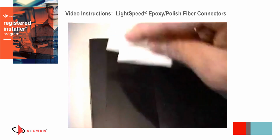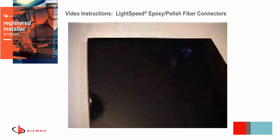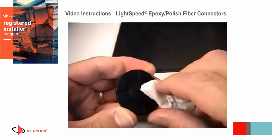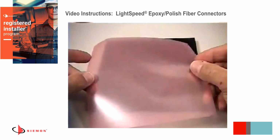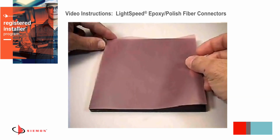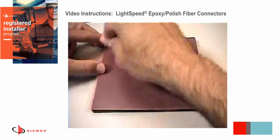Prepare the polishing pad and puck by cleaning with an alcohol wipe to remove any debris that may adversely affect the polish. Position the pad onto a flat surface with the rubber side facing up. Place the pink 3-micron film onto the polishing pad with the glossy side of the film down and remove any air that may be trapped between the pad and film.